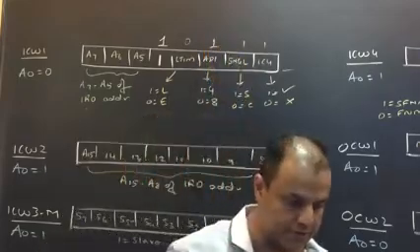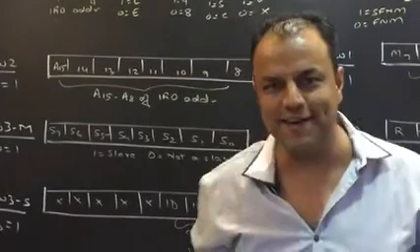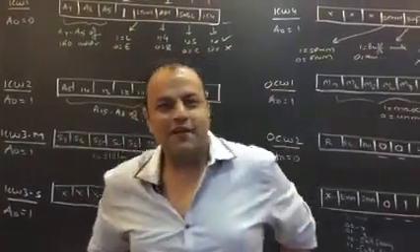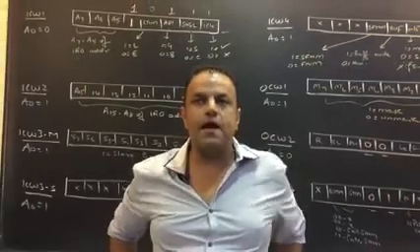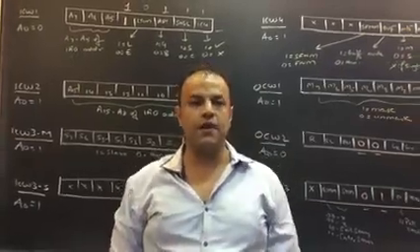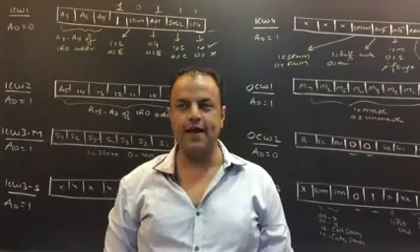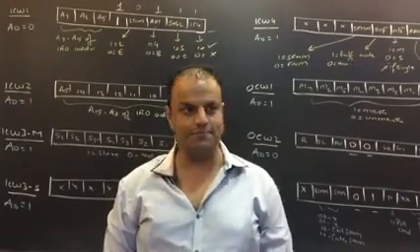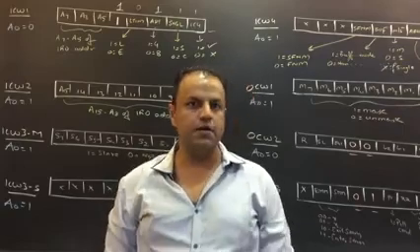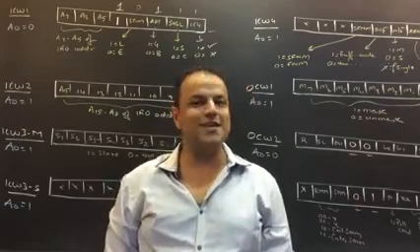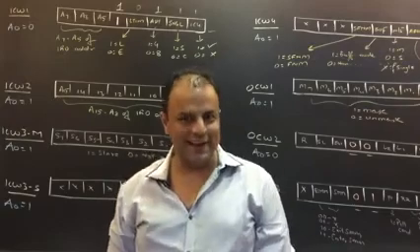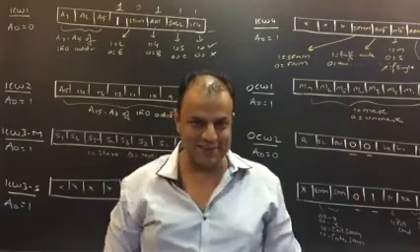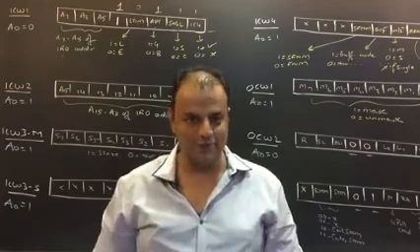Sometimes they do this. They say initialize 8259. I'm going to ask you questions, okay? Pay attention. Initialize 8259 as follows: edge triggered, and so on. ISR address of IR0 is 4000. ISR address of IR2 is 4008. And the rest of the information. Now, what did you understand from this? ISR address of IR0 is 4000. ISR address of IR2 is 4008. So what is the address interval? 4. I'm sure you got that, right?